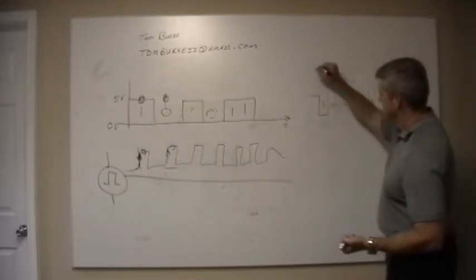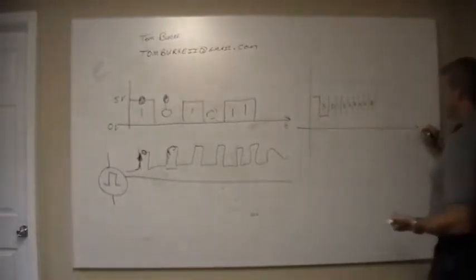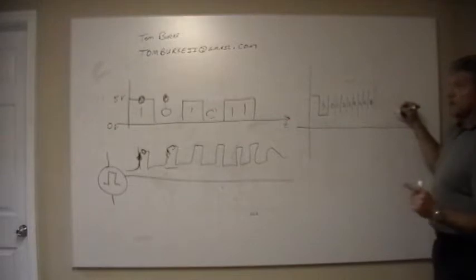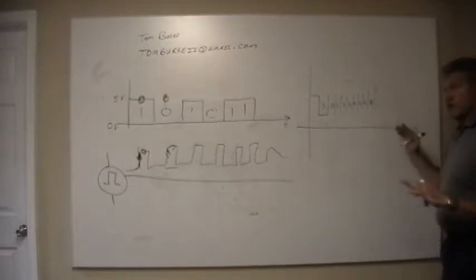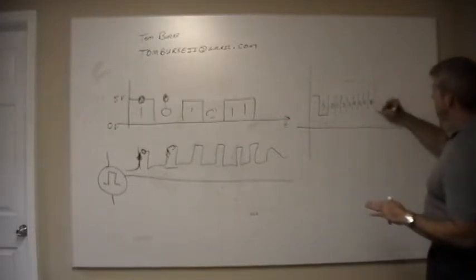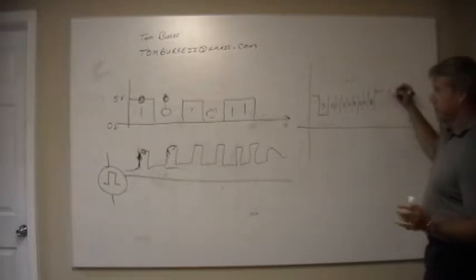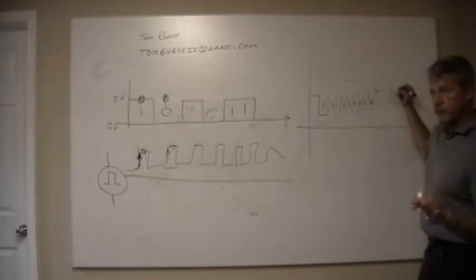And again, this is in time going that way, so that actually happened first. And no parity bits is what we usually use. And then one stop bit. And it could be 1, 1.5, or 2, if I remember right. And I think there's some applications that can do 3.